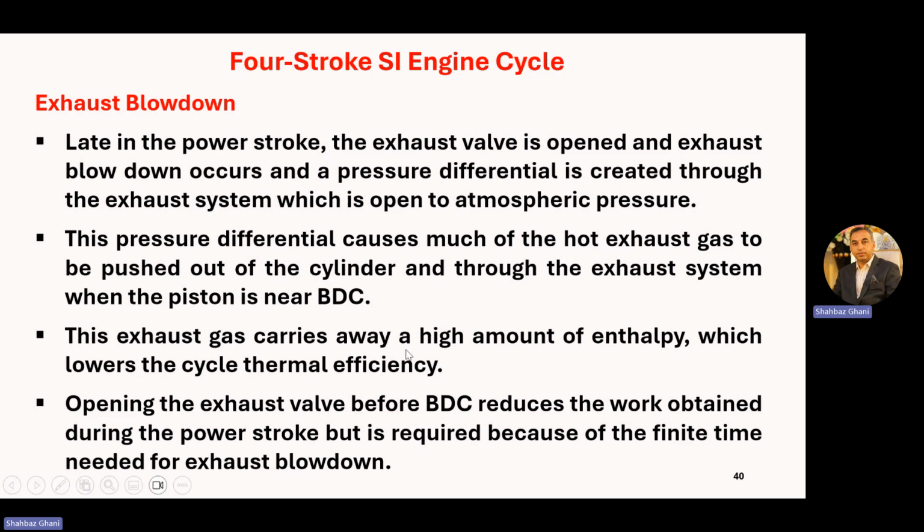These exhaust gases carry away a high amount of enthalpy, which lowers the cycle's thermal efficiency. Because of the hot gas emissions, they take a high amount of enthalpy with them, which lowers the cycle's thermal efficiency. Opening the exhaust valve before BDC reduces the work obtained during the power stroke. The power stroke is basically the work done, but the exhaust valve is opening before BDC, so the work obtained during this power stroke is reduced